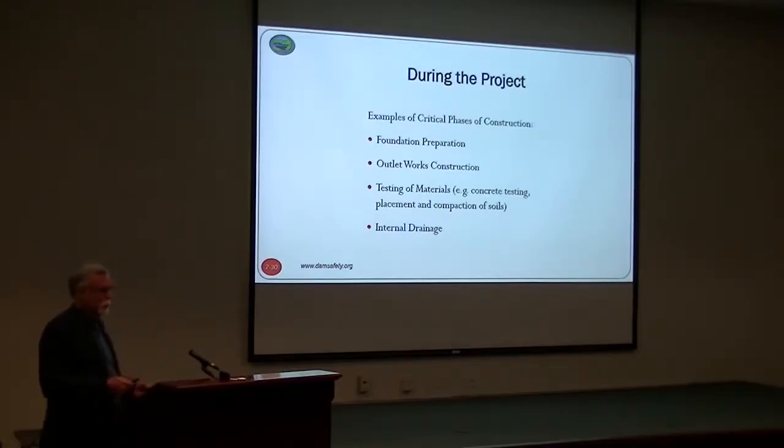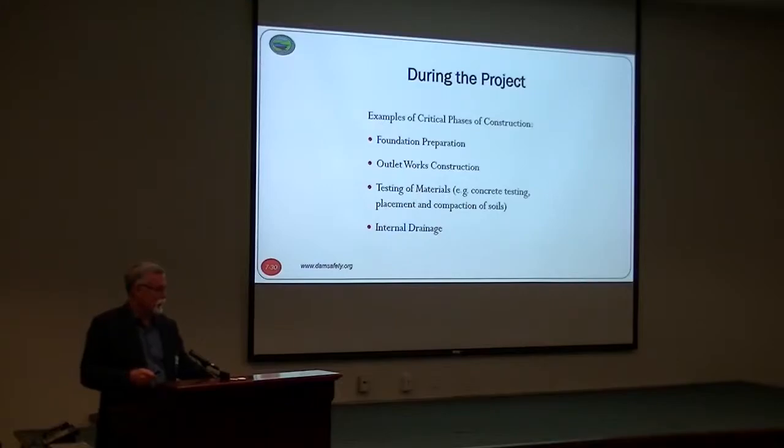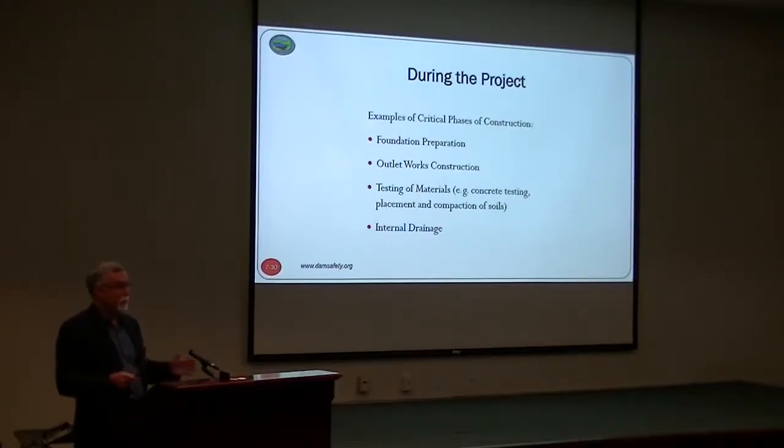Critical phases of construction. I said before, a lot of times with dams, it's not the dam, it's the foundation of the dam that's the problem. So when you build a dam, when you clear it, and you excavate the mud and the stumps out, you've got to make sure that the foundation is prepared to accept your dam, whether it's earth or concrete.